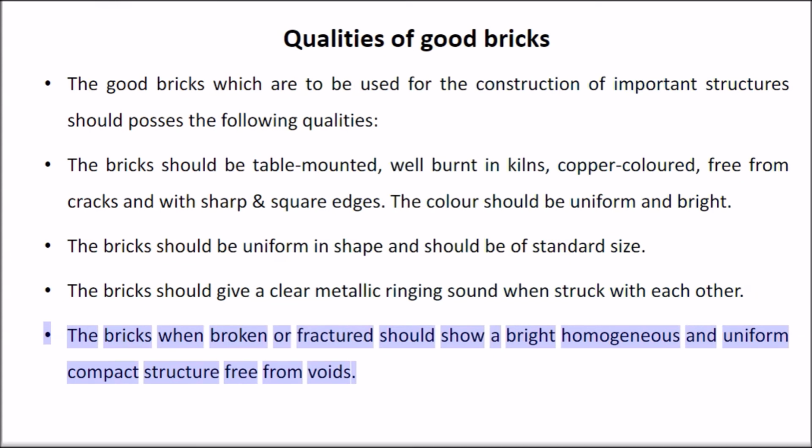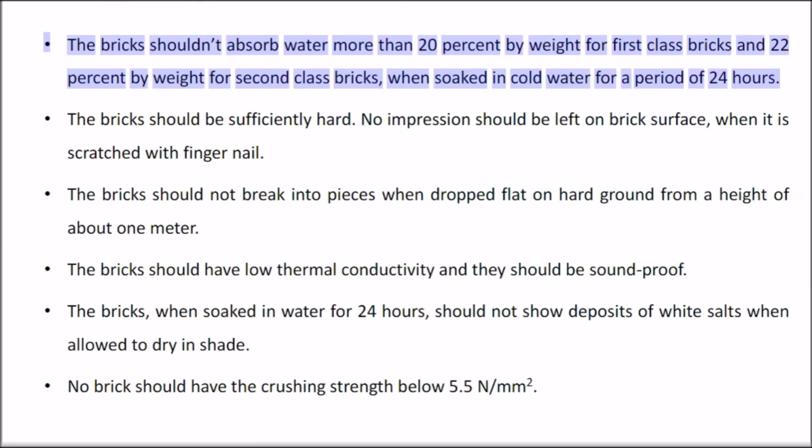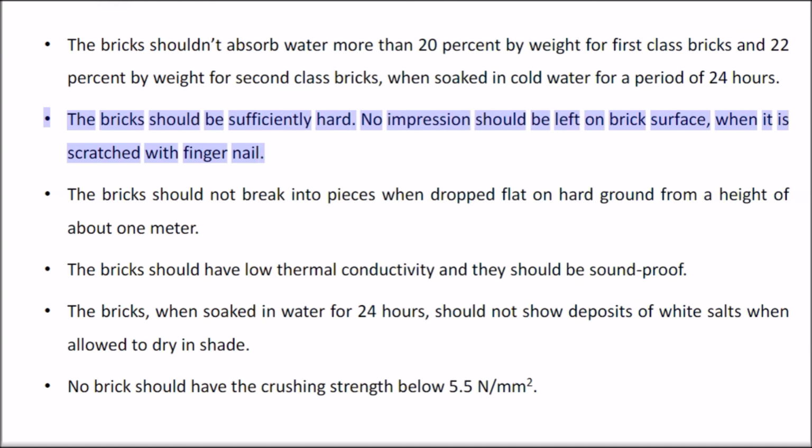The bricks when broken or fractured should show a bright, homogeneous and uniform compact structure free from voids. The bricks shouldn't absorb water more than 20% by weight for first-class bricks and 22% by weight for second-class bricks, when soaked in cold water for a period of 24 hours. The bricks should be sufficiently hard. No impression should be left on brick surface when it is scratched with fingernail.